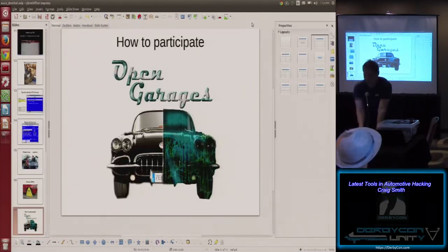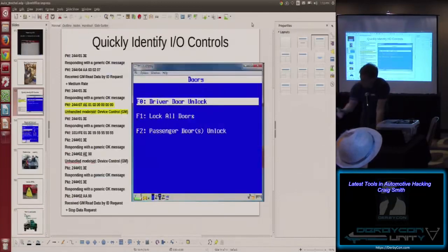Another one, yeah, we got time. Another thing you can do is, let me go to that one slide. Here you can see where I sent a door unlock, and here's the packet that unlocks the car doors. There are other things when you get information like the VIN. The way dealership tools work, they don't do the standard mode 9 to get a VIN, which is the generic UDS. That is how the other scan tool from Bosch would work.